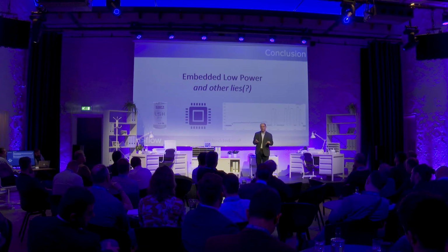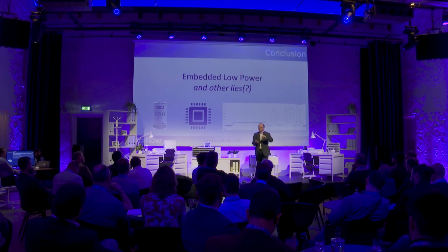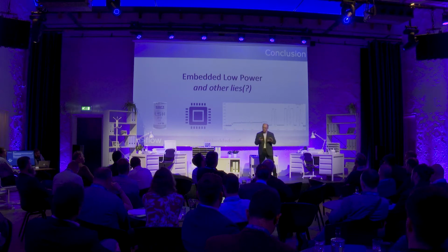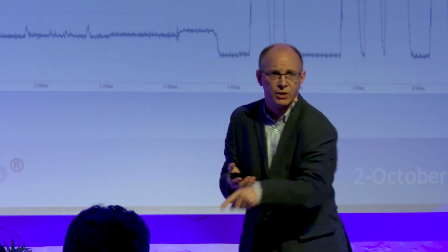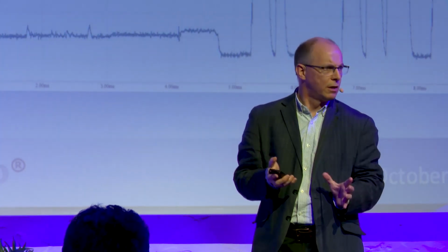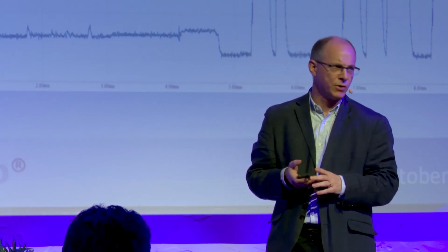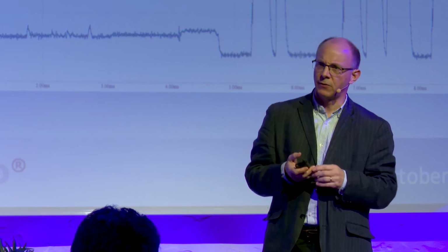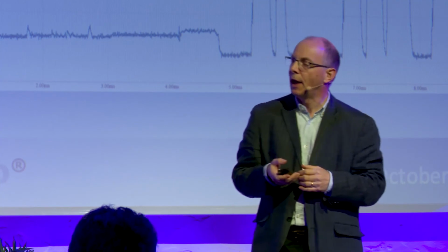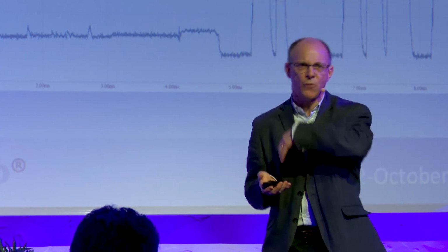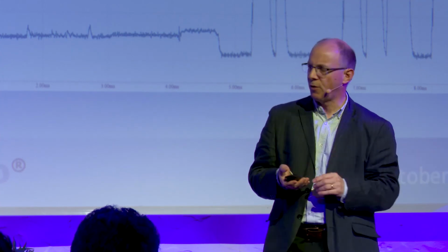And then once you've got that decision, okay, this part looks okay, then the only thing you can do is develop a customized low power board which has been optimized for measuring low power, and then actually do some real environmental tests to see what happens in this particular software, in these particular currents. And that gives you a feel for that particular chip. And now you've got to make 1 million and hope that that particular chip was representative. The semiconductor vendors will be able to share some of their characterization data to give you a feel for how these curves look over temperature.